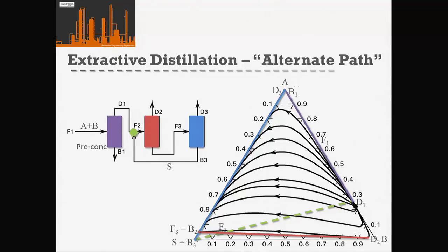But if you have a maximum, you would put it in with the feed. But it makes it a lot easier for drawing on our diagram if, no matter where we actually physically put it in the column, we mix it with the feed first, because that allows us to define that mixing line.